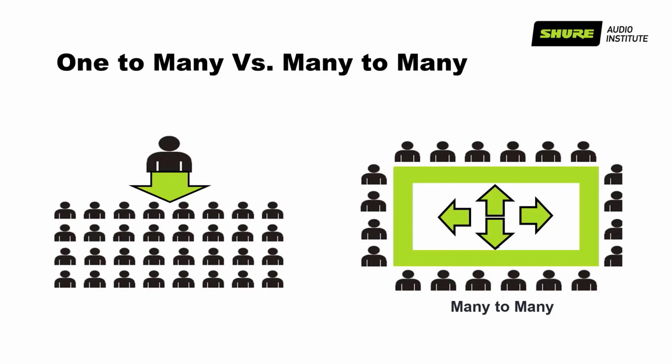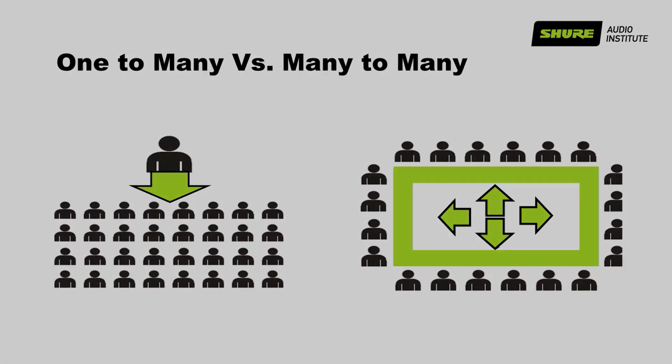And this complicates things a little bit because now you don't just have 1 or 2 microphones up front and then a bunch of loudspeakers in the room. Now you've got a microphone for everybody because they all have to be able to talk equally well. And you've got to have loudspeakers near everybody so that everybody can hear. This gets to be a little bit more difficult because you run into issues with feedback or echo in conferencing situations, and those discussion and conferencing systems can be great for this because everybody gets their own personal microphone and loudspeaker. So the feedback problem is solved, the echo problem is largely minimized, and everybody hears consistently in the room, whether it's 10 people or 1,000 people.